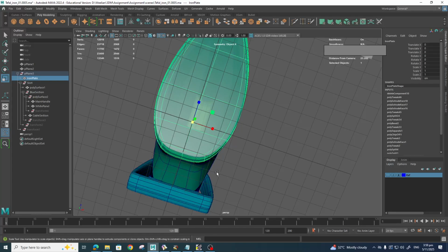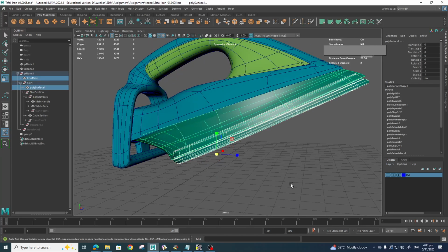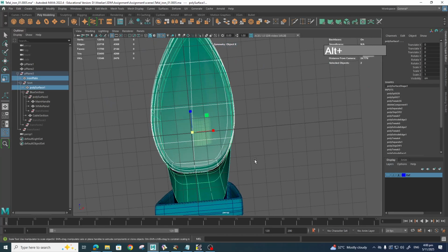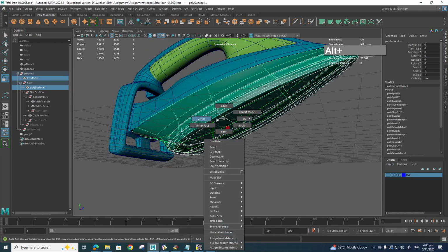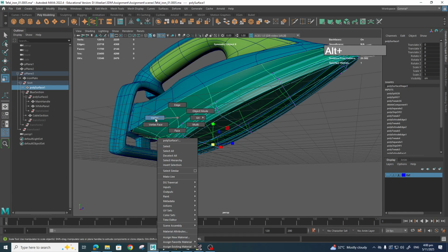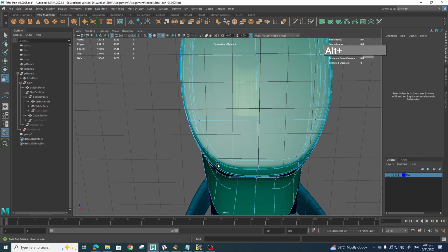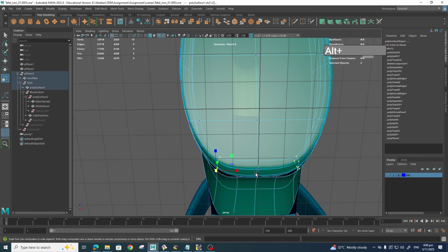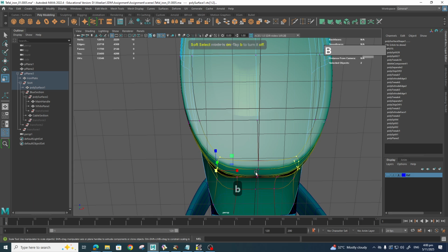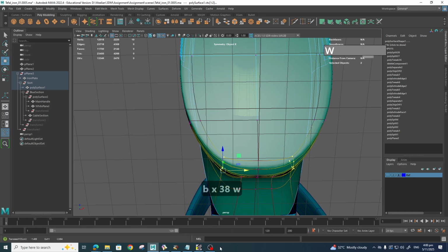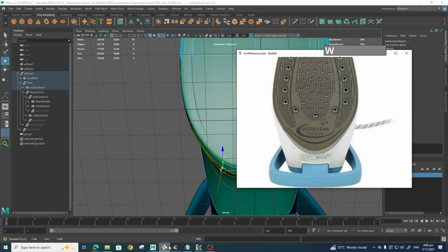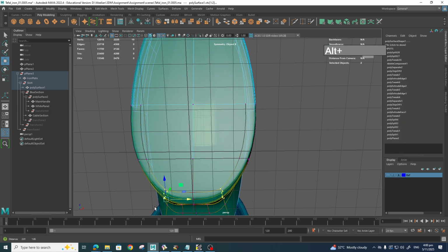So again, I'm going to use the technique of selecting both the skirt and the hot plate, and then right mouse click and go to vertex mode for both, and then selecting this group of vertices here, then using soft selection with a certain range, and then we're trying to move this inward so that it matches the general shape of the reference here.